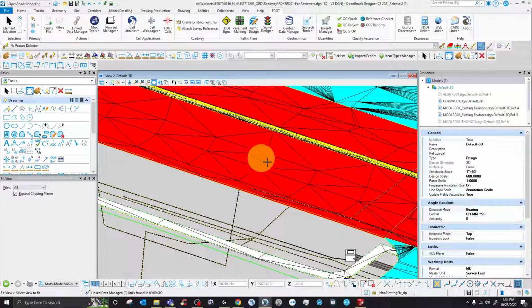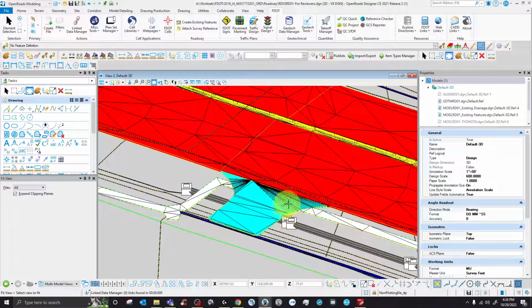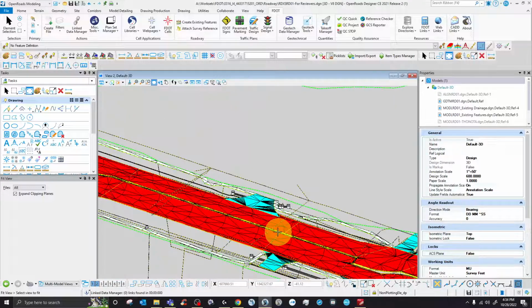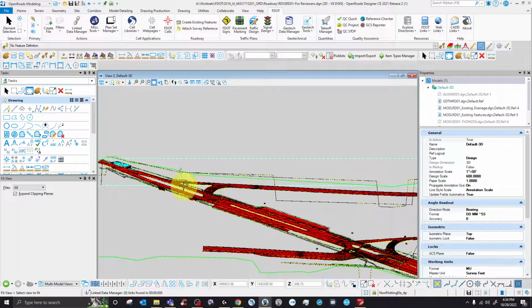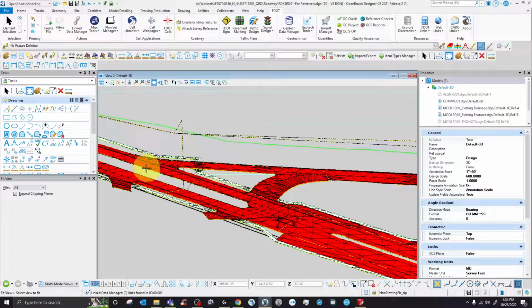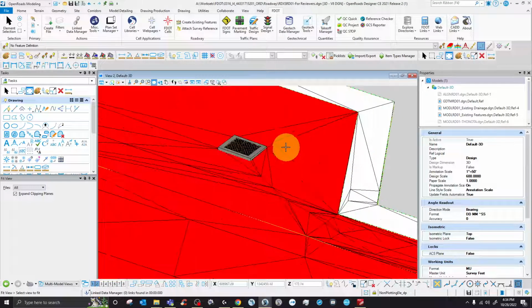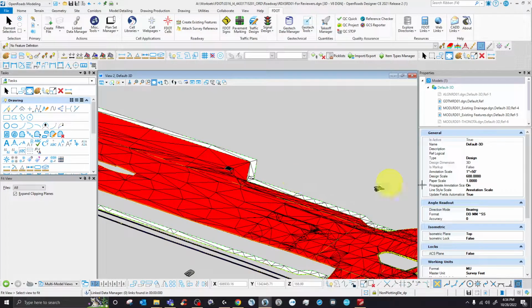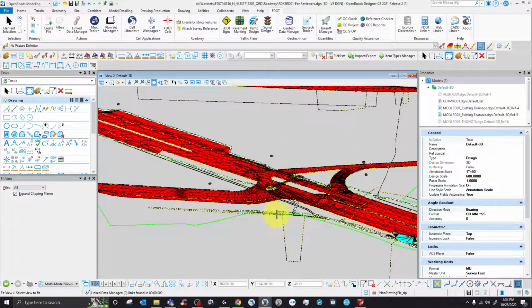Basically the existing pavement, existing sidewalk, existing side streets, existing traffic separators, because all these are gonna show in the cross section. As you see here, all the existing that we need to show. That's why I keep calling them, even look at the catch basin, that's why I call them like a cake. And then the top layer of the cake is our proposed model.